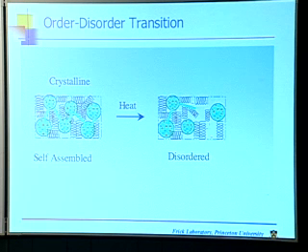that looks something like this cartoon over here, where I have the spaghetti, which would be the polymer material, and I have these pools of salt water or acidified water, which are the green things. And the pools are connected by these channels, like I showed you before. And what I'm trying to show you here is I have a fair amount of order to those pools, and that's why I get X-ray diffraction. So there's actually a periodicity to these pools. Okay, it's self-assembled. It's crystalline.